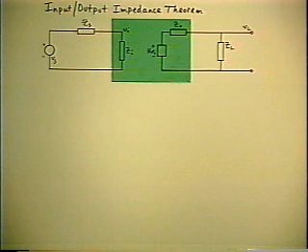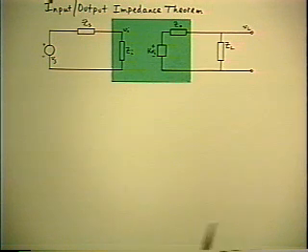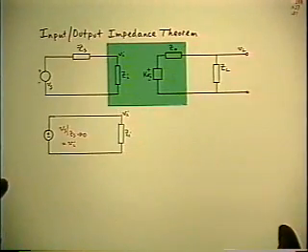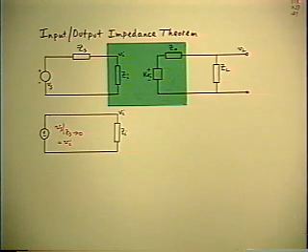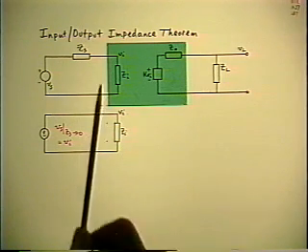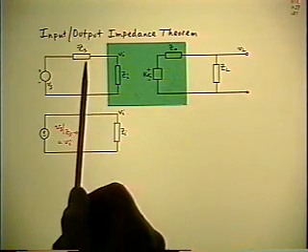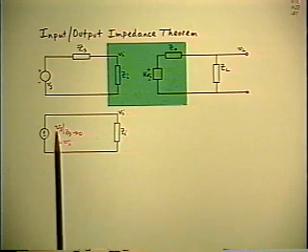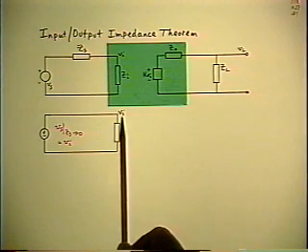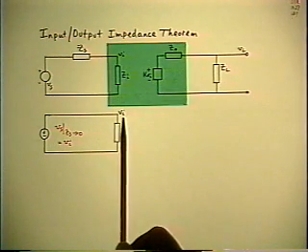Okay, there's an input impedance theorem. You're beginning to anticipate pretty well by now that duality helps a lot with these things. So, the derivation of the input impedance theorem follows the same sort of argument. We do some work at the input end now instead of the output end. The first thing we do is we say, let's let the source impedance go to 0 and ask, what source voltage do we have to apply in order to get a certain value VI at the input to the system?